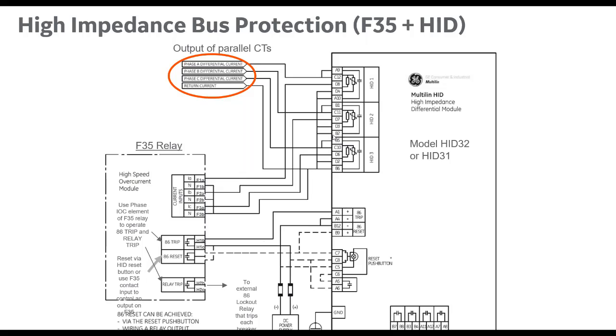The other option is you can have a variable resistor, and with the variable resistor, you need to know all the details of your short circuit, your CT burden, CT performance, and you can calculate what we call the stabilizing voltage, meaning the voltage that will be impressed upon the high impedance coil when the CT completely saturates. Once you get that stabilizing voltage, you can calculate what that stabilizing resistor is, and you can select a value. We could do both options.